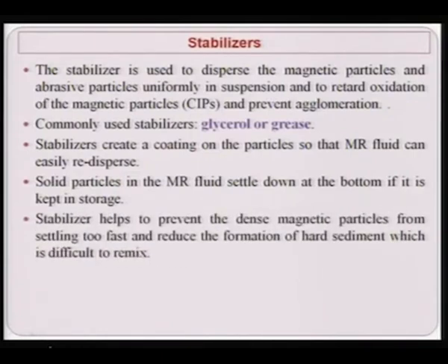Stabilizer has to prevent the dense magnetic particles from settling too fast and reduce the formation of hard sediment, which is difficult to remix, because we do not want hard sediment to form of the magnetic particles or non-magnetic particles. Otherwise, mixing of these particles becomes very difficult, and one should be very careful before using this MR polishing fluid.